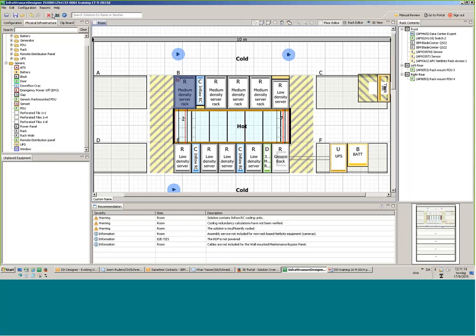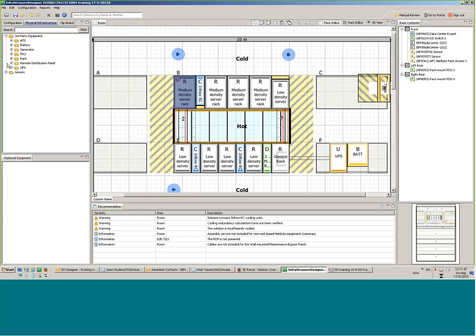Then up here I also have the possibility of deselecting the cable calculation. So if you do a bigger solution and you move rack after rack and you have already connected some of it, you can cross this one, move all the racks, which is much faster, and then select it again before you save, and that's it. Then it's just calculating once and not all the time. So it's just to make it more fluent.